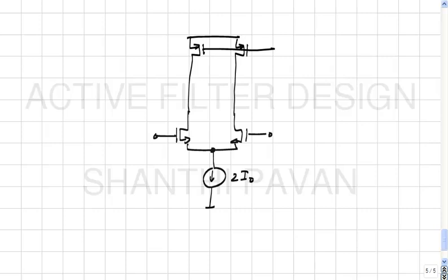Okay. Again, we see that the PMOS transistors, which are supposed to act like current sources, not only add noise, they also degrade the DC gain. So what do you think we can do to fix the problem? Okay, the easiest thing to do is to cascode the PMOS current sources. Okay.